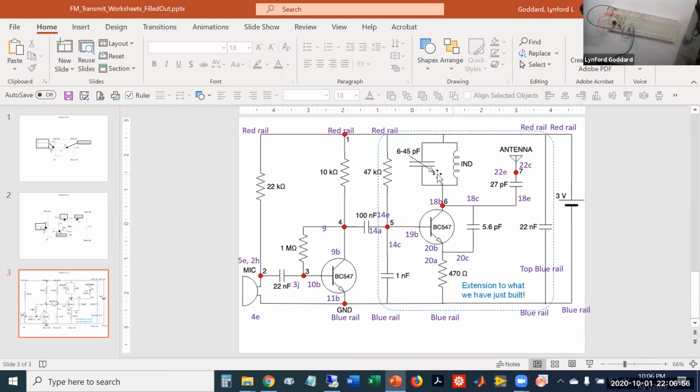So basically this resists, or I shouldn't say resists, there's charges on the capacitor plate that try to move and flow current into the inductor, and then the inductor opposes that flow, and it basically builds up a magnetic field, and then that magnetic field stores energy, and then that stored energy can go back into the electric field associated with the capacitor.